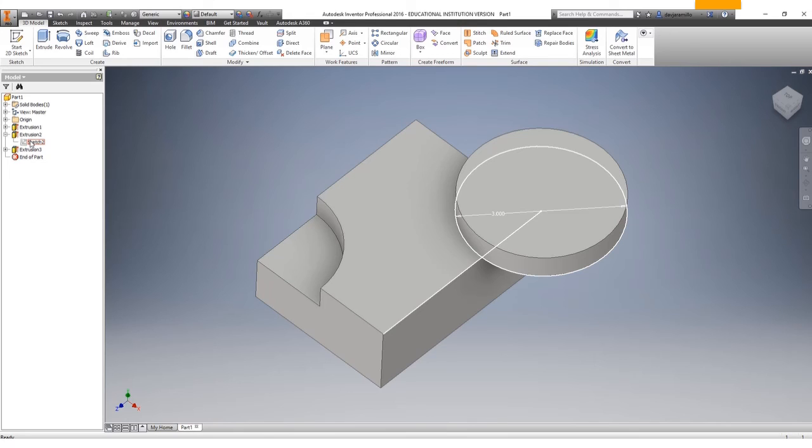Once you extrude a sketch, that sketch is done. And that's why I'm saying I've seen students sit there and take forever drawing this elaborate sketch out, and then they only extrude a couple pieces of it, and that's it. They can't use that sketch no more. And that's why I'm going to keep stressing to you guys, it's going to be piece by piece. You try not to overdraw on your sketches.